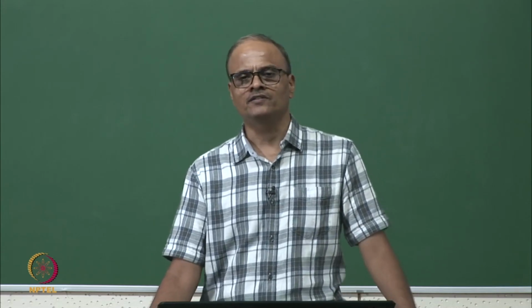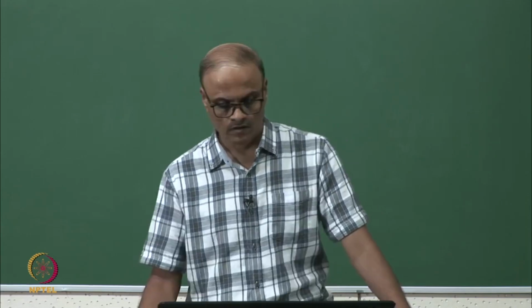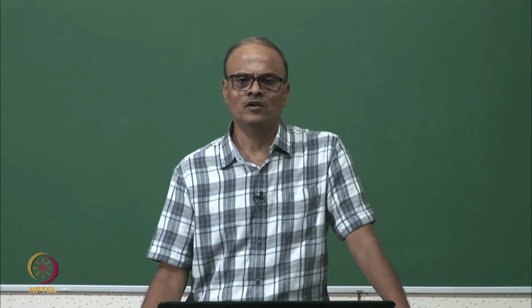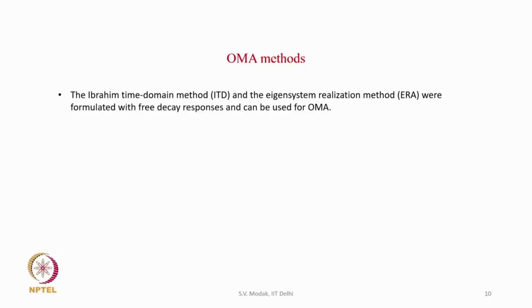So, these free decays or random decrement can also be used to find the modal parameters. Let us now look at what are the different methods that have been developed for operational analysis. The Ibrahim time domain method and the eigensystem realization algorithm were formulated with free decay responses, and therefore, they can be used for operational analysis.